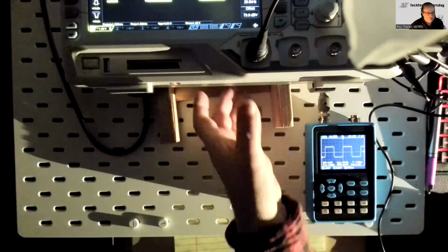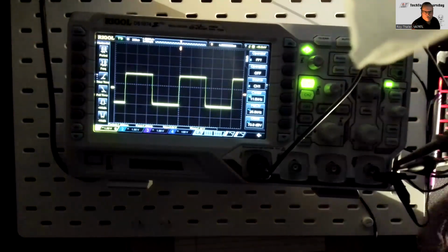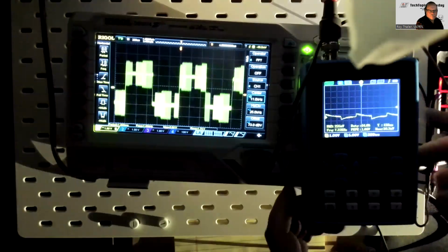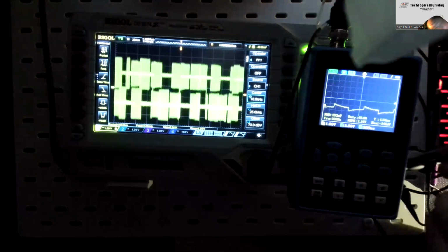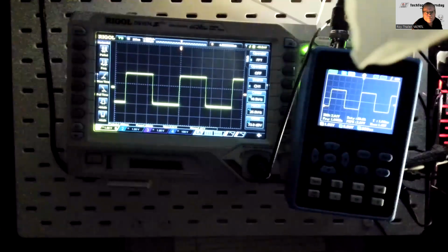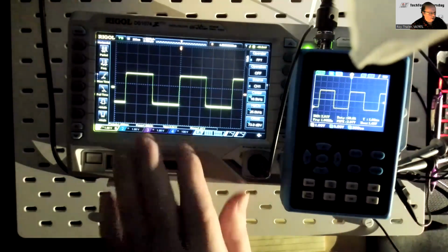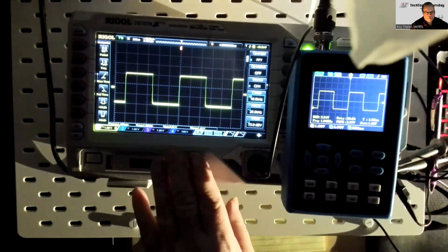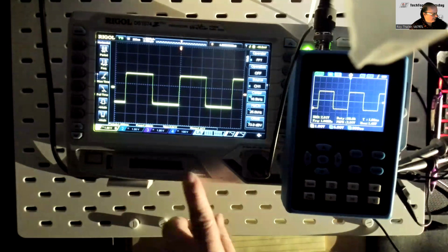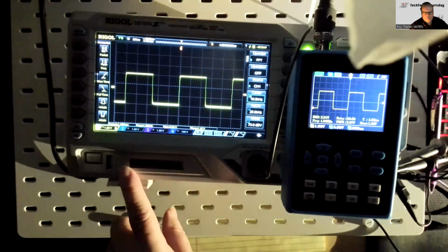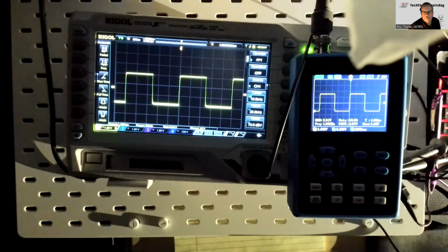So you can get a big scope like the Rigol, or you can get something like this. I disconnected one of the grounds here. This one actually has a higher frequency range than the Rigol. This one has 2 inputs. This one has 4 inputs. This one does a lot more mathematical variations, and also you can plug in your logic analyzer down here where you can look at signals. But this is a good scope for measurements and gives you all the values that you want.